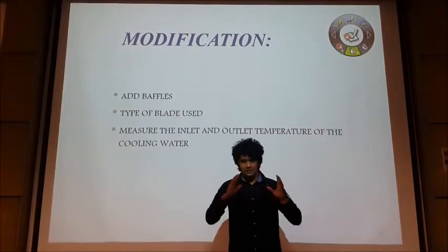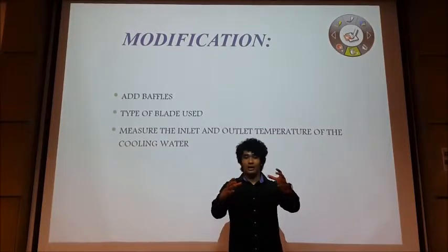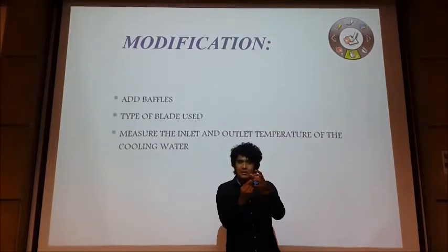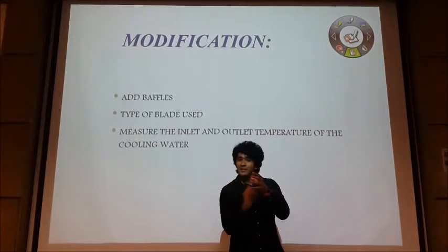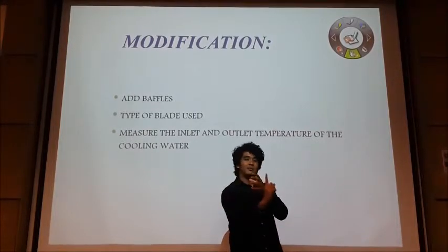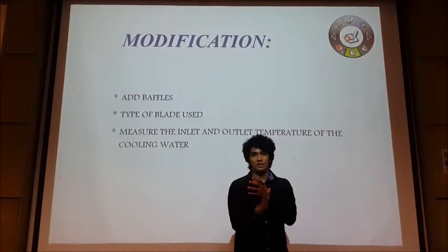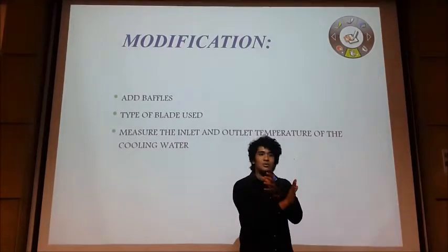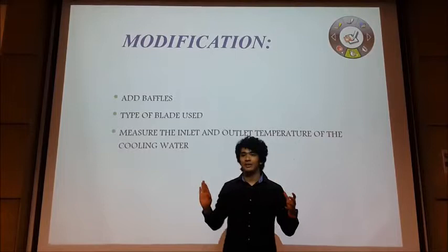Alright, the reactor design was like this. The glass wall, and inside was the cooling jacket. The stirrer was actually in the middle of the cooling jacket. So when the stirrer spins, the outside is spinning much slower, or not even spinning at all. That's what we said in the discussion earlier. The particles are being held at the side of the wall. So there's no reaction taking place on the outside, the unreacted region area.